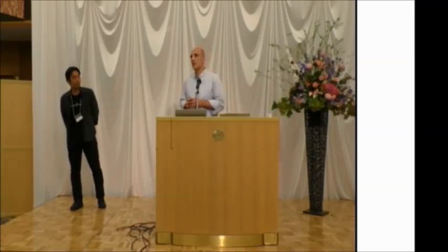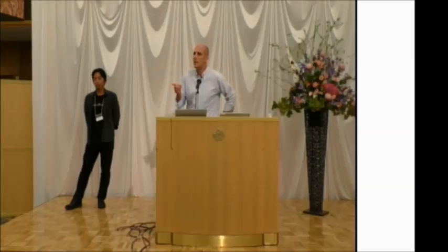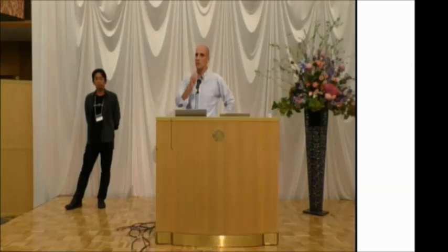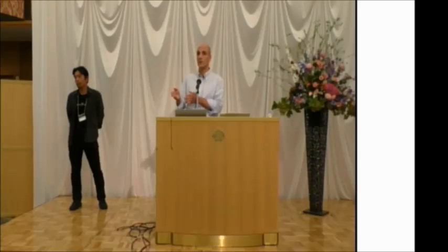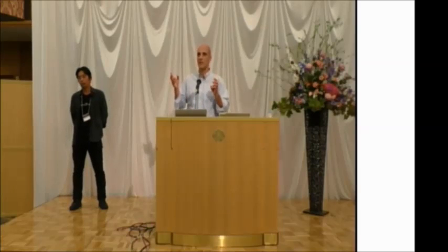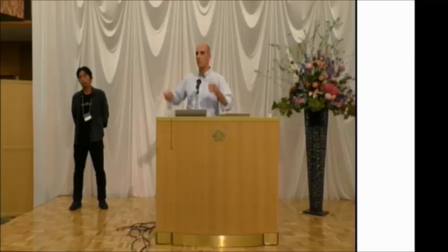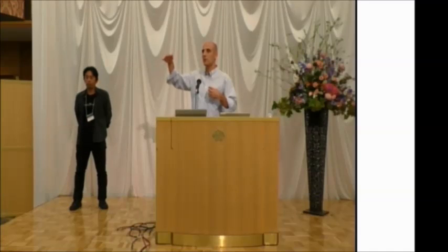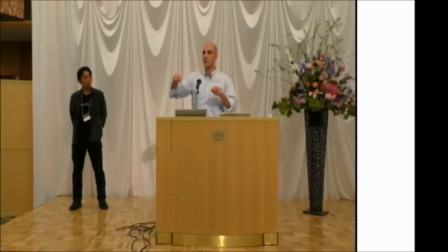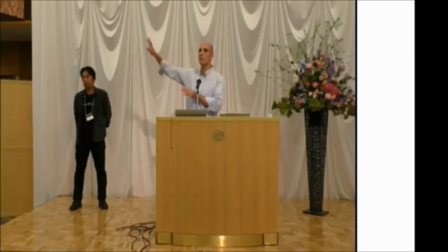I do not have an example in supercritical flow, but I guess, in supercritical, it's even more difficult. Yeah, more tricky, because the waves are also faster. It depends on how supercritical it is. Because if you are close to the critical condition, between say 0.8 and 1.2 in Froude number, the waves are messy and very fast. Also, the water depth waves, the perturbation of the water depth, travel at the same speed as the perturbation of the bed and also the sorting wave. So you have to go very far.